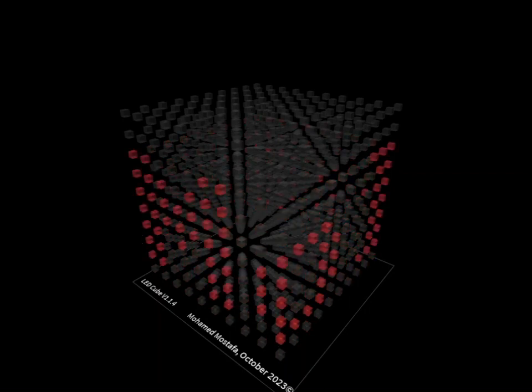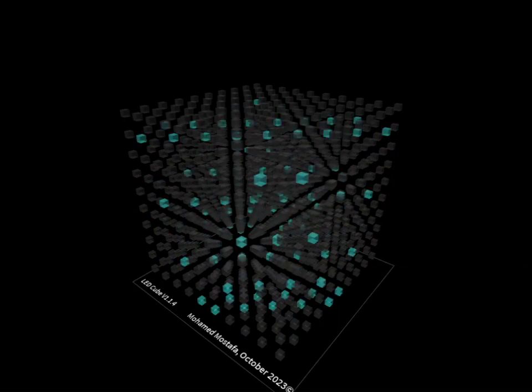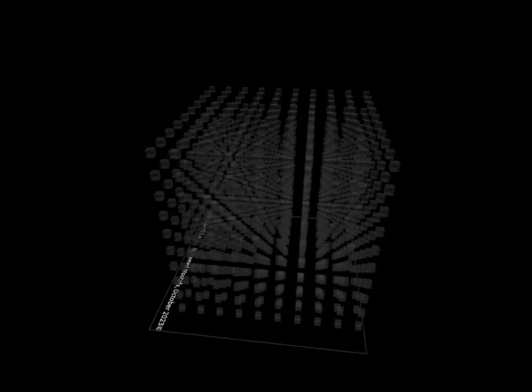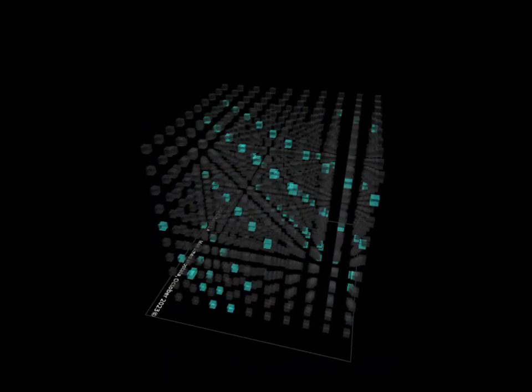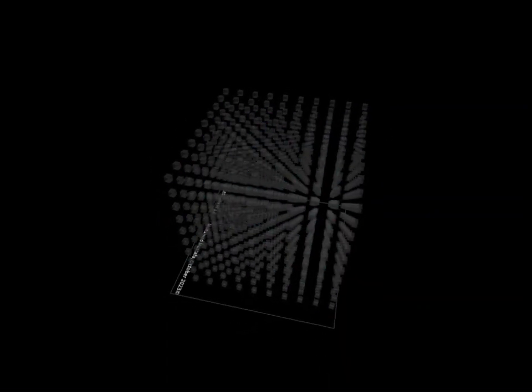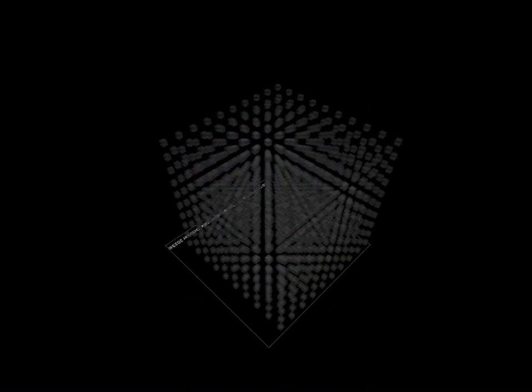The job of the latch is to serve as a kind of simple memory. The latch can hold 8 bits of information, and these 8 bits are represented on the output pins. Consider a latch with an LED connected to output Q0. To turn this LED on, apply V+ to input D0, then pull the CP pin low, GND, and then high, V+. When the CP pin changes from low to high, the state of the input D0 is latched onto the output Q0, and this output stays in that state regardless of future changes in the status of input D0, until new data is loaded by pulling the CP pin low and high again.